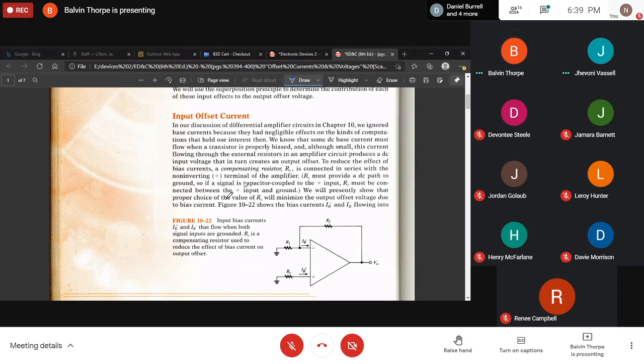When you have just the creation of the amplifier, the junction potential is a result of movements of electrons being attracted to holes, and current will flow even when we have not biased the transistor. And then of course you're going to have a junction potential, and that junction potential has to be overcome through proper biasing to forward bias the diode or the transistor junction. If not, it will not be forward biased.